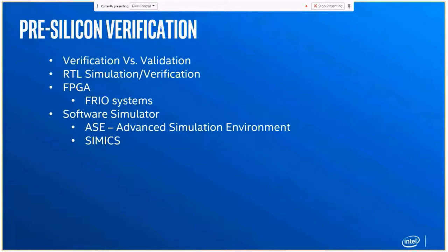For example, you can think of the DPI block. There may be a bunch of registers that are all configured to do XYZ in the actual silicon. We totally ignore that because that's not really needed, right? We just take the gist of what that block is doing, and ask: if a customer develops an application and it runs here, can it faithfully run on the silicon? We keep asking that question repeatedly to develop the simulator.